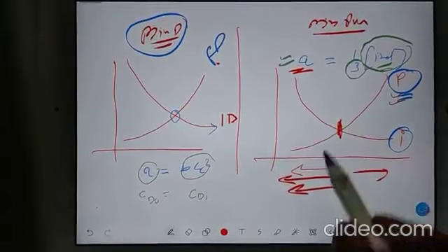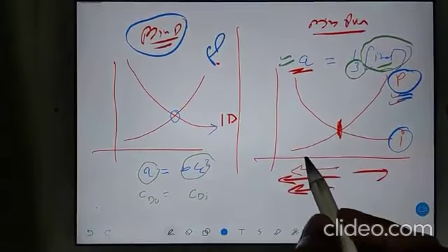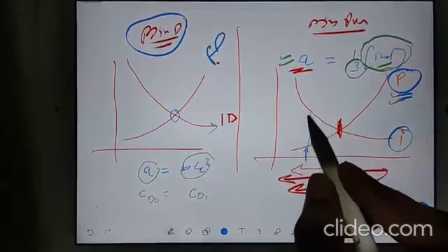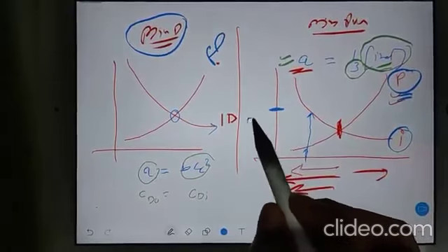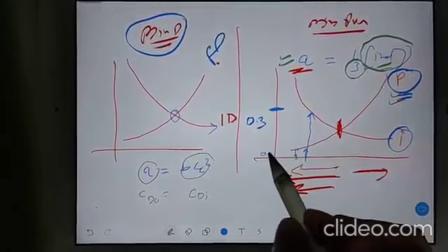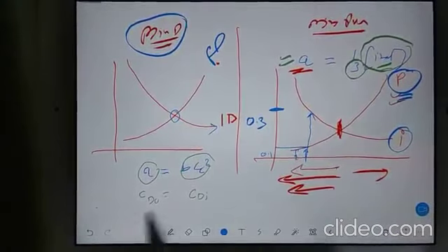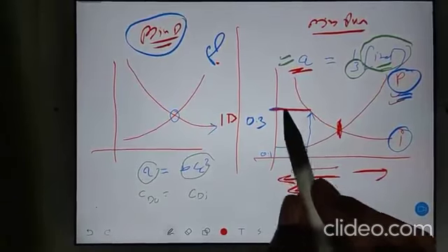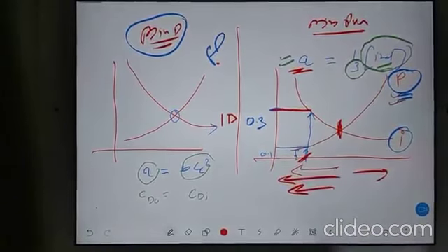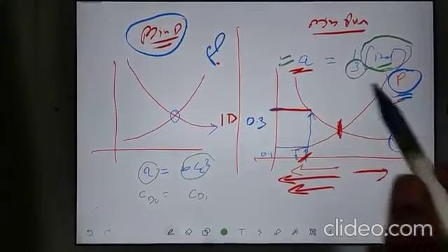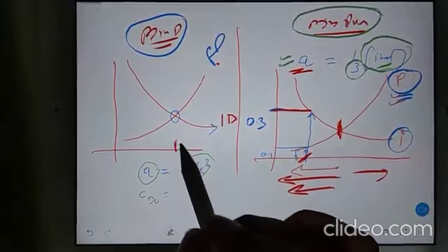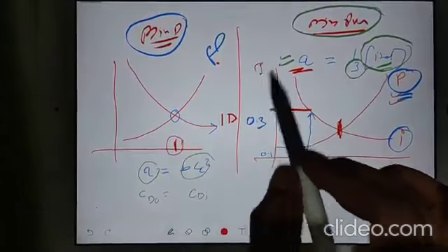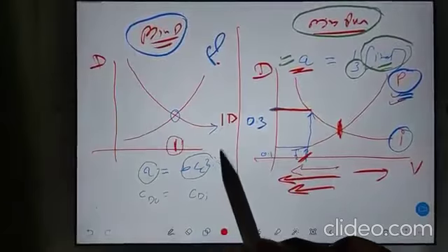So you have to check the height. This height you have to compare with this height. Suppose, just imagine this height is 0.3 and this height is 0.1, like here. It means exactly this is the point where your minimum power condition is occurring. Now go to the more physical side. What was this point? Keep in mind, we are discussing the drag versus velocity graph.